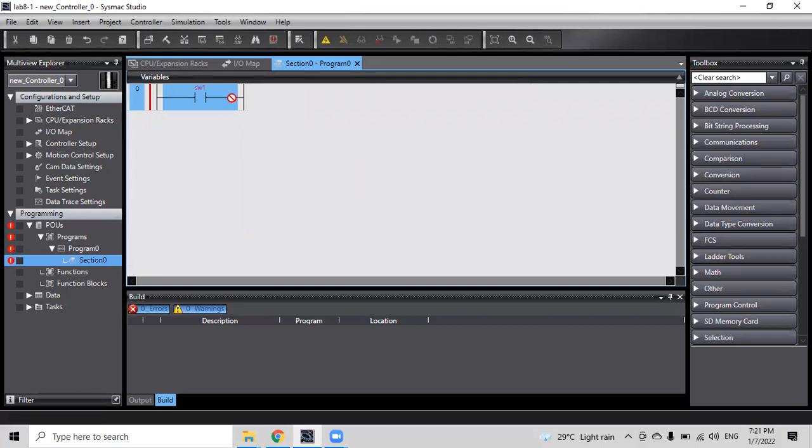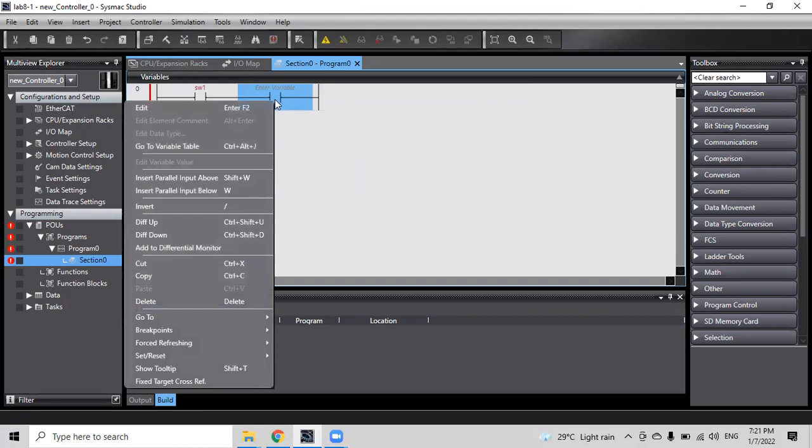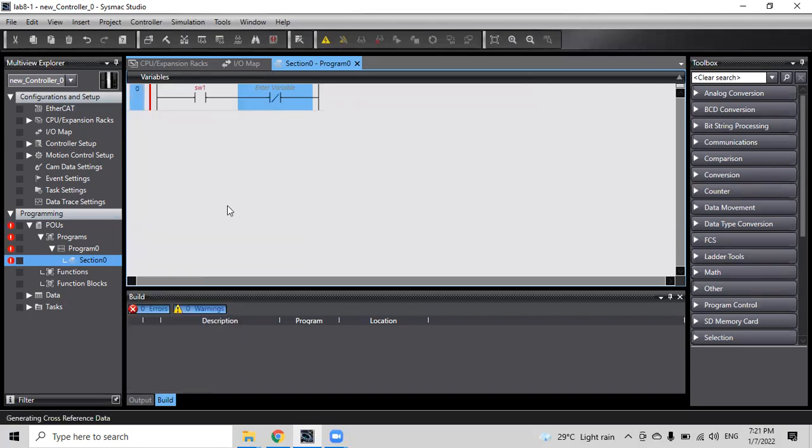All right. Once you finish the first one, you just go behind and highlight this one. Type C again, so you can insert another new input. But this time the logic is opposite, right? So you right click on the input. Can you see the invert? You click on the invert. All right. So you can see now we have the opposite logic here. And once again, we need to rename this one as SW2, which is switch 2.